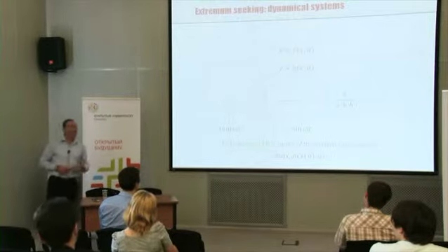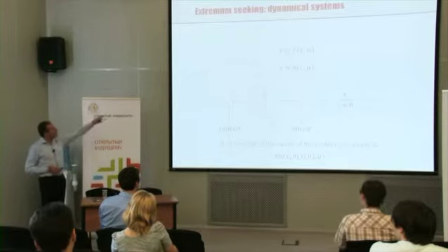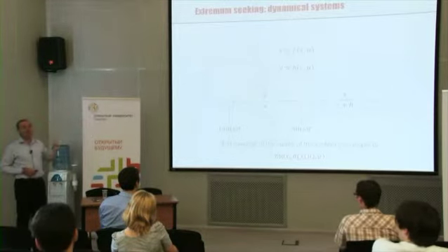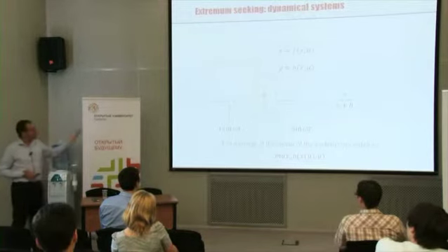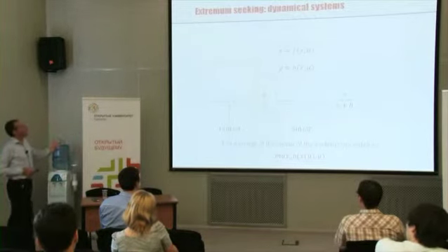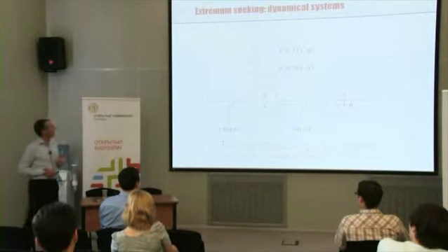You would like to maximize the quality of what you produce, and so you can achieve this with this loop, which is called an extremum seeking loop. You seek the extremum, you seek the maximum in this particular example of the input-output map of a dynamical system.